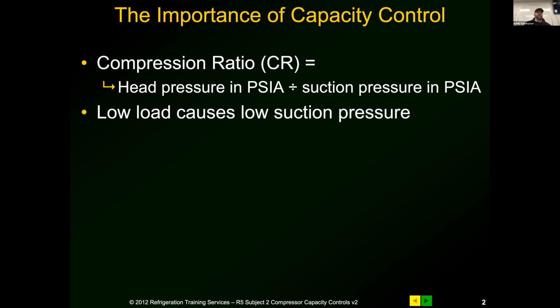What that's telling us, in more granular detail, is how much volume of cool gas per stroke that compressor is getting. Because if you have a really high head and a really low suction, on that downstroke there's always a little bit of discharge pressure in that cylinder. If it's really high, it has to drop pressure in order for that reed valve on the suction line to open. And so it's less new gas volume introduced per downstroke.